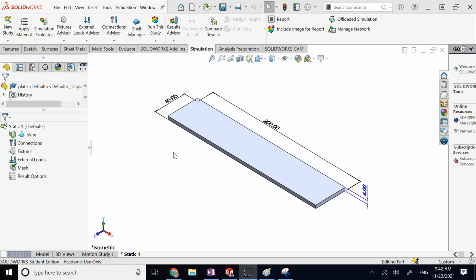And that's where you can convert the problem into 2D by using shells. So shells are 2D elements basically. They look 3D, but they have zero thickness. Or if in addition to the y that does not change anything, the direction for z also, which is the depth, does not change anything, then you might bring the problem further down and make it only 1D along x, and that is what we call a beam. So a beam is converting the 3D object into 1D basically.